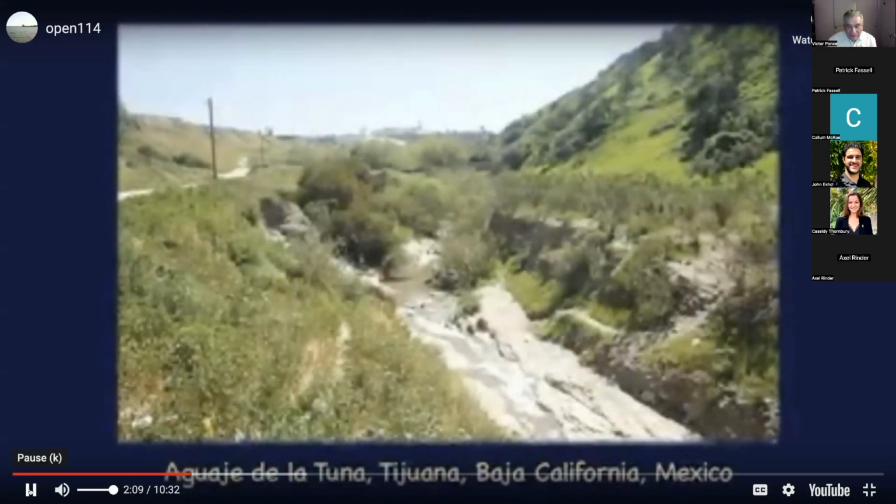This photo shows the effect of a sediment retention dam in a small creek: a reduction in sediment load downstream of the dam. There are two dams out there, one there and one behind it, where the arrow is. They were put in in 1992 to hold on to the sediment. What they didn't realize was that if you hold on to the sediment, the water becomes hungry downstream. And that's exactly what happened.